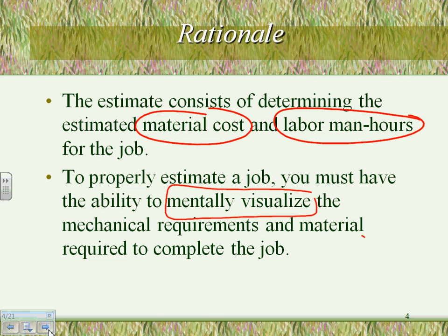Knowledge of the material required is very important, guys. You have to understand that if you go in the wall, you have to go up in the ceiling 8-10 feet and run over and down to the panel, maybe 6 feet. Most of the time when we do takeoff, we're doing it on 2Ds, right? You look at 2Ds, but you're taking off a 3D, so you have to drop down every time.